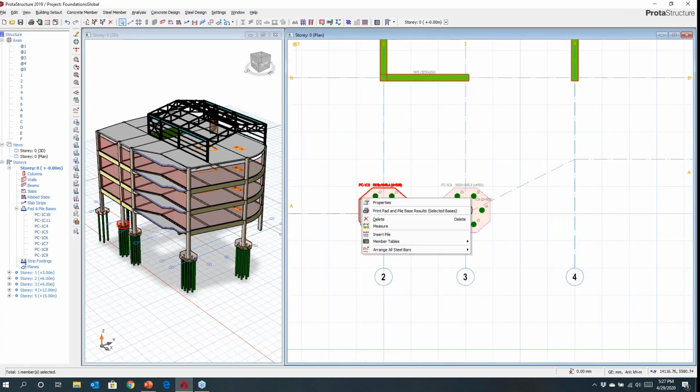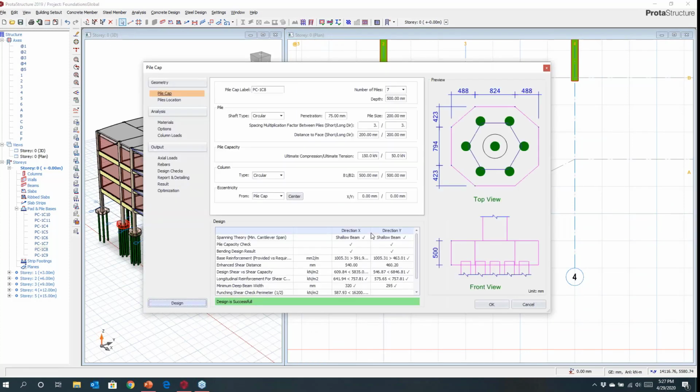can just select it, and you can interrogate the properties here. Within the pile cap, you can individually play with specifications here. So if you wanted to use maybe a different pile set for a given pile cap, you could. If I wanted to maybe increase the size of the pile for this particular pile cap effectively and the allowable working loads or the ultimate capacities and reduce number of piles that may be required, I could do that.